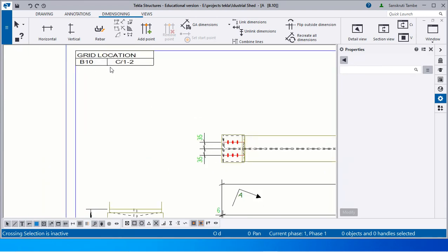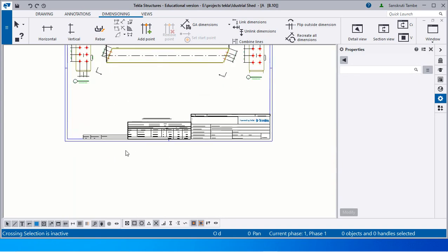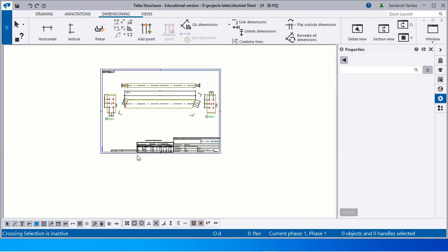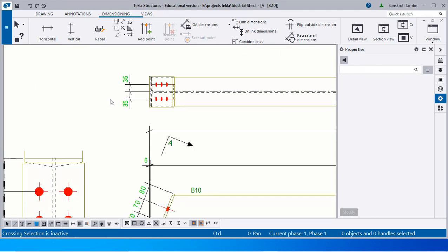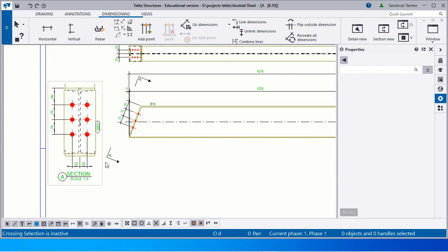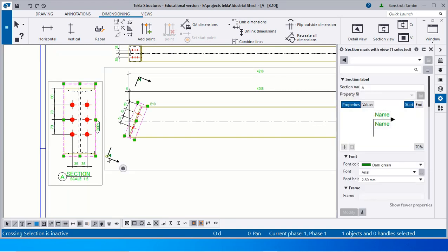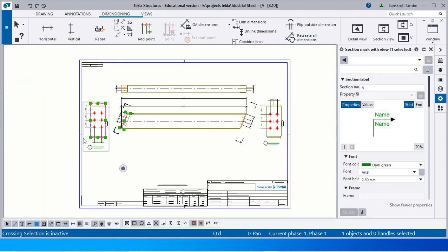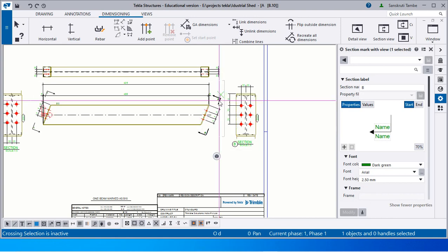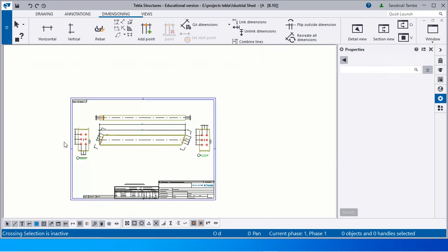And this is the beam number 10. All the details related to the part mark and all that is mentioned over here. You just need to check all the things. If you want, you can make the required changes. Like here I am moving this part mark in here. Just have to drag this, okay, then save.